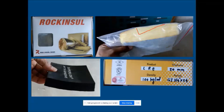Because this fiber material is very fine and it could be inhaled, and this will be dangerous for the respiratory system, or irritation in the eye may happen. So this should be covered. You must have seen this kind of glass wool always covered with a panel. You must have seen a timber panel like this, and between it and the wall, if this is the panel and this is the wall, in between we can use glass wool. So it should always be covered, right?